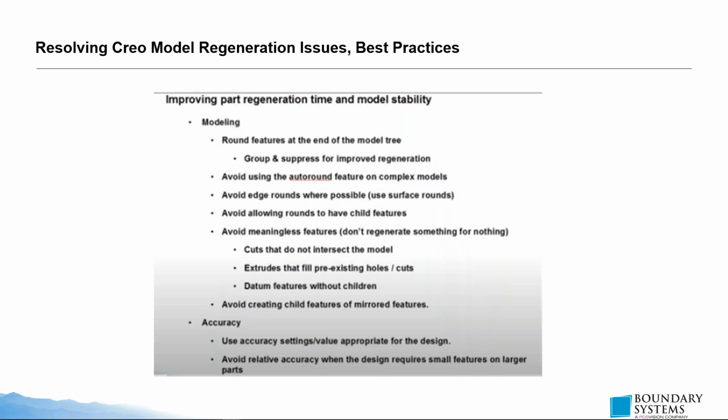Also, extrudes that fill pre-existing holes or cuts. It's not easy to see sometimes on the model, but that has been done in the past. I know that, but I know you guys are better than that. So we're not filling in those things. If we don't want them, we go through and delete them. I'll also say there's an option for that in model check that will actually check if somebody has filled in a hole or a cut with actual geometry.